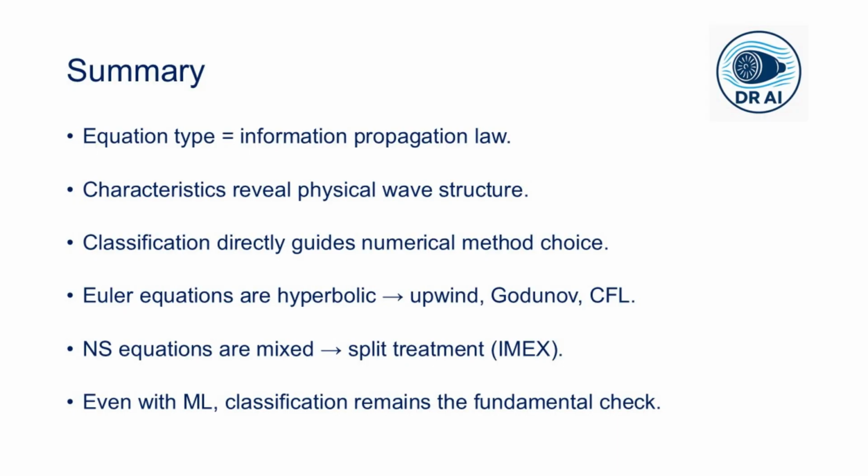Now, let me wrap up. PDE classification is not a mathematical abstraction, it's a logical foundation of the CFD algorithm design. The three types tell us how information propagates, how to set the boundaries, and which numerical scheme to choose. Characteristic analysis of the Euler equation reveals the wave mechanisms and gives the theoretical basis for the shock capturing schemes.